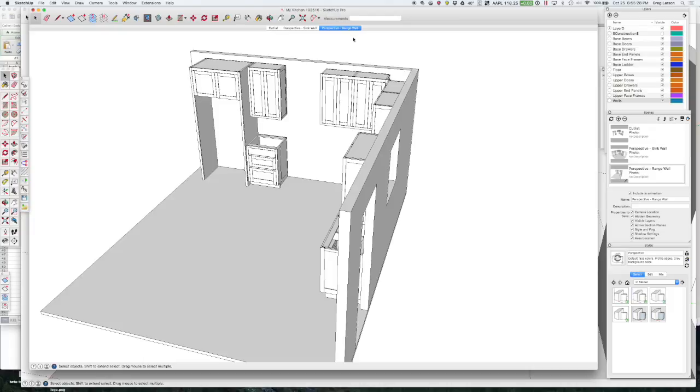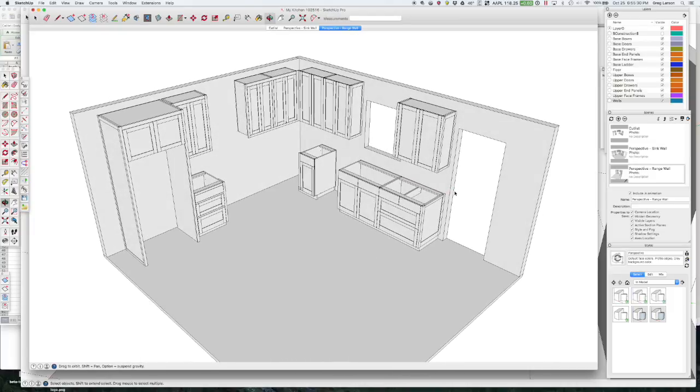But what we are going to want a few of is elevations and sections. So let's create a section first. And we're simply going to use SketchUp's section plane tool down here. And when I click on that, I get this plane that flips around depending on what I'm touching. And I want to take a plan view section of the lowers, so I want to be in this orientation.